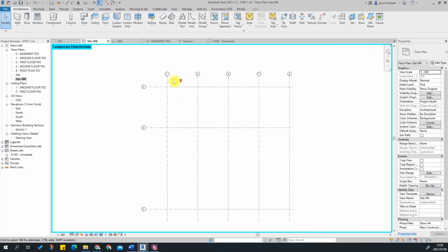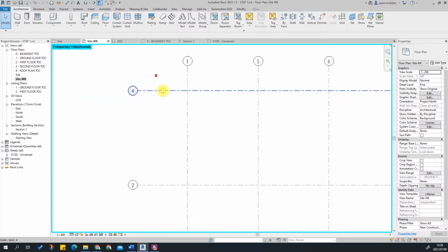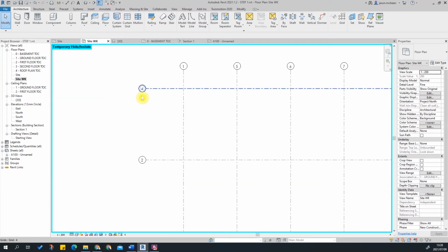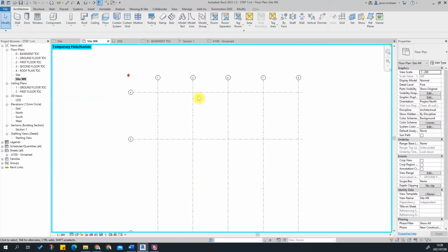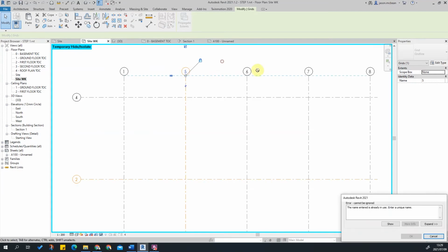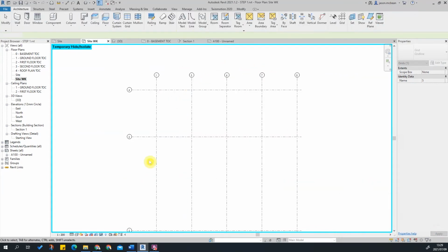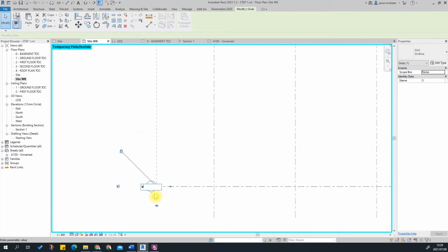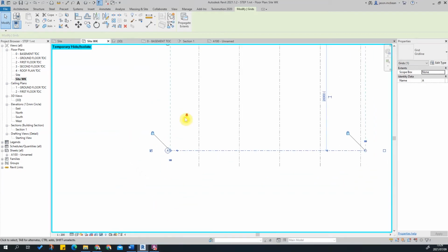So with the grid system, if they change direction, you either use numbers and letters, or numbers and letters separately. You either have a letter and number combo if you have a lot of grid systems, but in this case, I'm going to stick with 1, 2, there's 2 already. So let's fix that first. So let's start here. This will be A, caps lock A. Okay, scroll up.